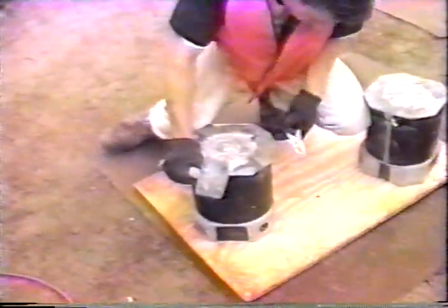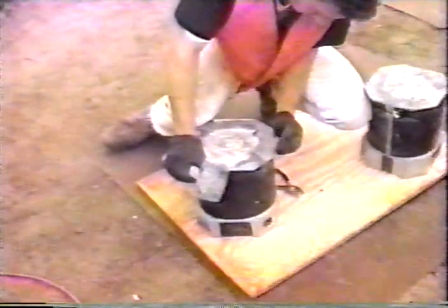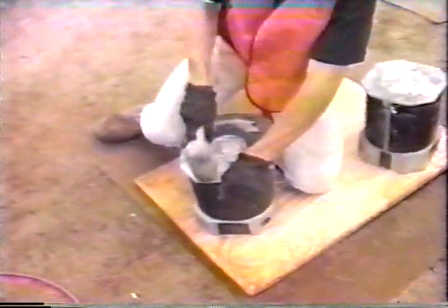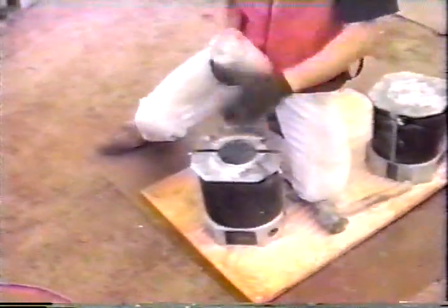At the end of curing time, the cylinders are demolded and made ready for testing. Demolding can be done easily by hitting the top of the mold with a rubber hammer to release the specimen. A portable compression machine can be used to test the cylinders in the field.